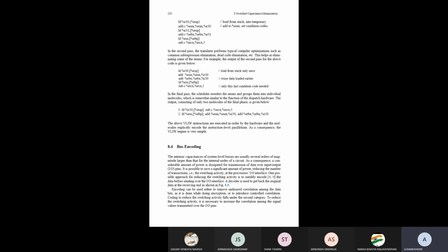Another possibility is a static one-to-many mapping of 2 power n unique code words to 2 power m code words. The current state of the encoder selects a particular m-bit code word for transmission, with several alternatives for a particular n-bit data word.